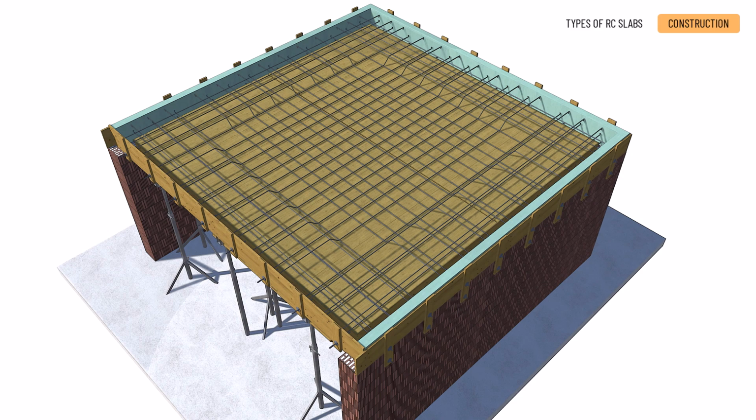Fifth, for ring beams, position and fix in the following order: the bottom longitudinal bars, the stirrups, and then the upper longitudinal bars. Sixth, for the top part, place top distribution bars on top of the ring beam bars. Seventh, distribute the main rebars at the top. Eighth, form the top mesh by connecting the main and distribution bars with tie wires.